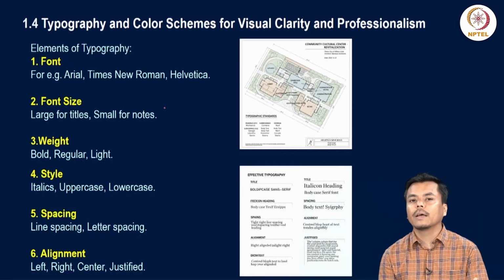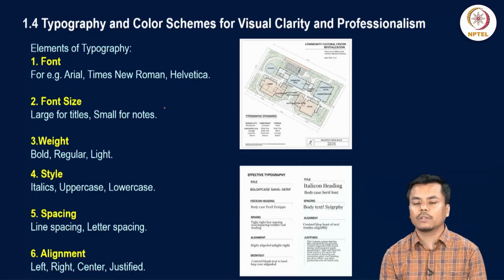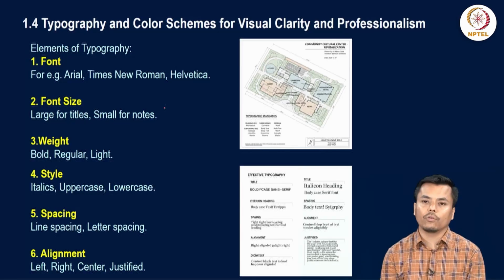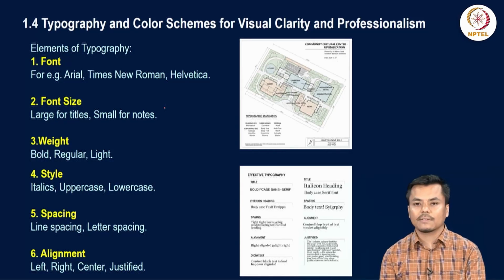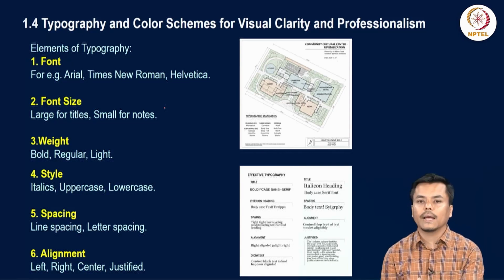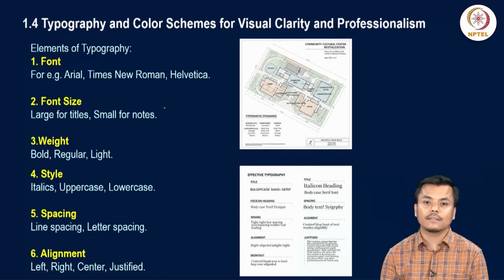It should not be such that it overpowers or shadows the drawing that you have used. Your font should be a very formal style of font, so that it doesn't overpower the drawing or attract more attention than the drawings that you have prepared. The font size should be in a particular order or hierarchy, as discussed. The main title of the drawing should be in a larger font than the other fonts like subtitles or subheadings or the notes that you have written.